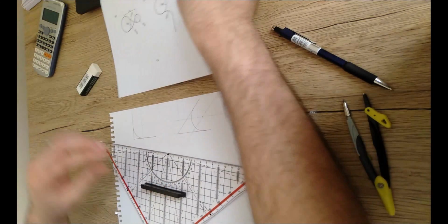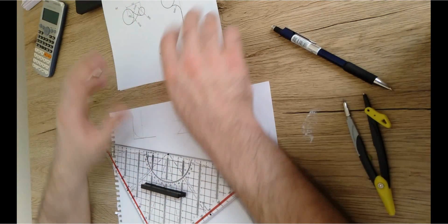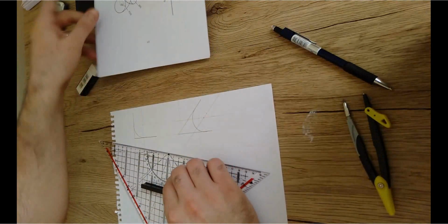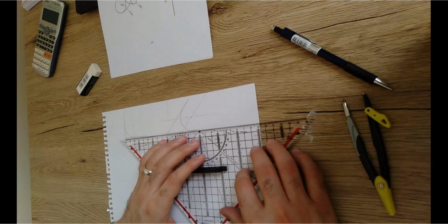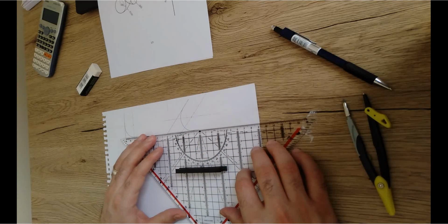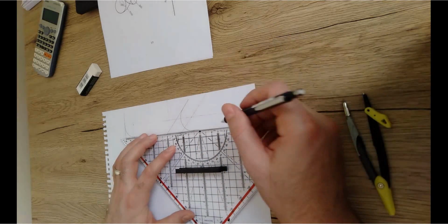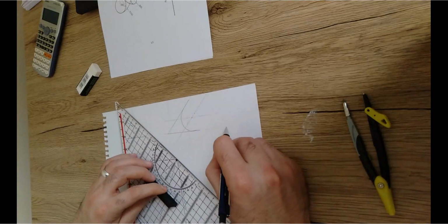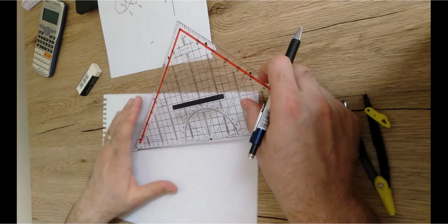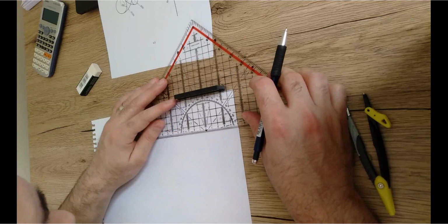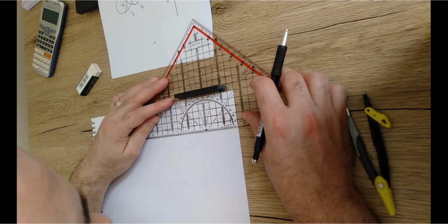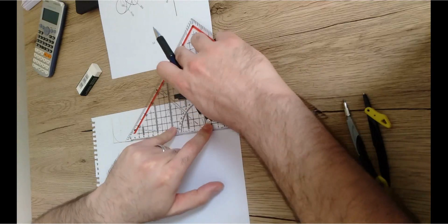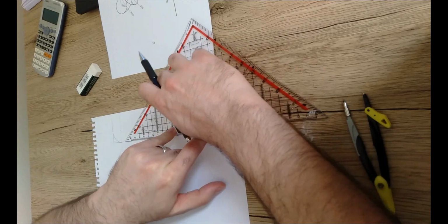Now let us move to the third curve here, which is this one. It has a horizontal line, and this angle is 120 degrees. So what I'm gonna do, I'm just gonna use the same line here, tracking over the same line. Then I'm gonna draw a very light line that is barely seen. Then from any point, for example from this point, I'm just gonna measure 120 degrees. So if you measure from this point, all of this is 90, then we would have 100, 110, and 120.